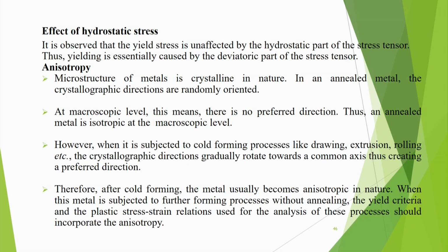In that case, there will be some deformation of the material, but as soon as you pull it out from the water, it will regain its shape. That means there is no permanent deformation. That deformation was only elastic deformation. So hydrostatic stress does not cause plastic deformation.